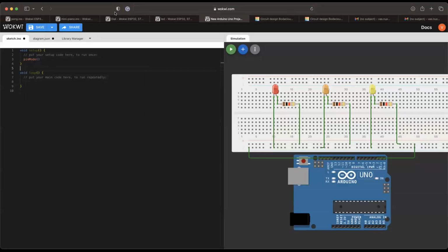I see it in your screen. No, I don't see it in my screen. I see it in your screen. Okay, well, you have to type it, pinMode. You just type pinMode in that. Pin, all lowercase, and then M is capital, and then pinMode. The pin is 2 that we're connecting to, and then the mode we have to set.